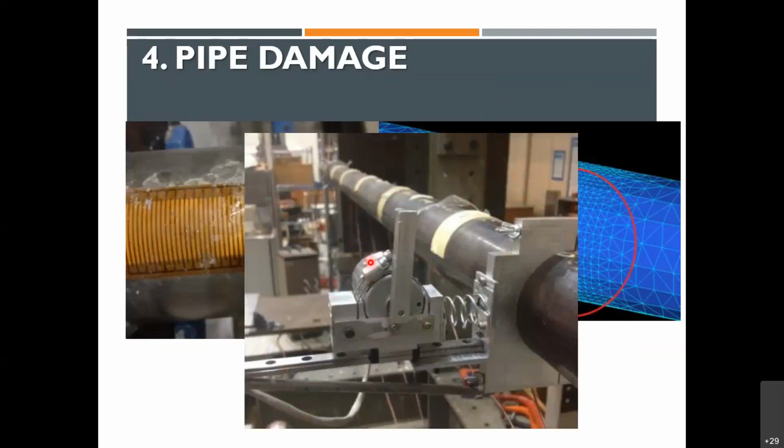We tried to figure out what the harvested energy is picking up. You might say, well, this is just a glorified version of strain, because it is the strain that the harvester is picking up and creating voltage. That's right. But if you put in a strain gauge, for each strain gauge you'd sometimes need a reference voltage. And with a harvester, this can be very flexible in terms of its application, and you probably can cut down not just on the external power, but also the wiring and the instrumentation a whole lot. And when this is not in a lab, it's far away somewhere, it does make a lot of difference.